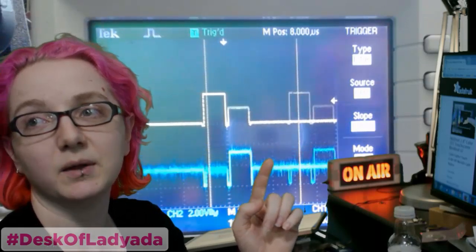So what it's doing is, you can see it's setting this pin high, and then measuring the analog voltage, and then it sets this pin high, and it measures the analog voltage on the other one. And then this is, if I move my finger in a circle, you'll see how the pins are sometimes fixed and sometimes analog reading.